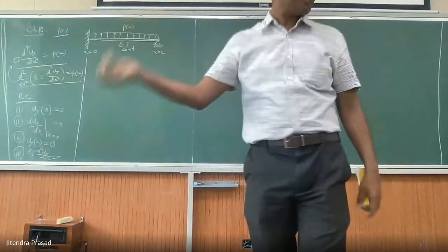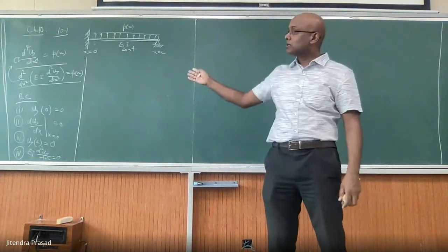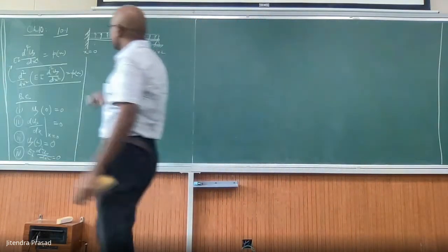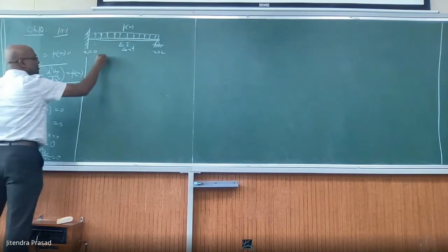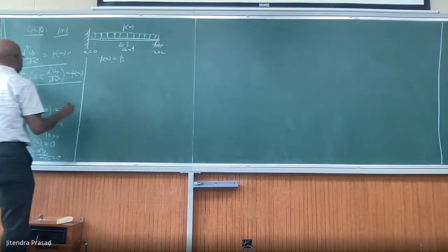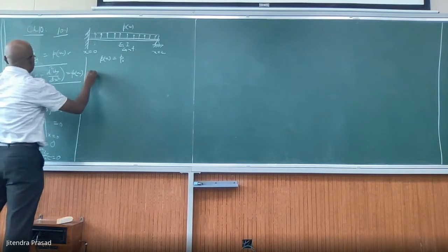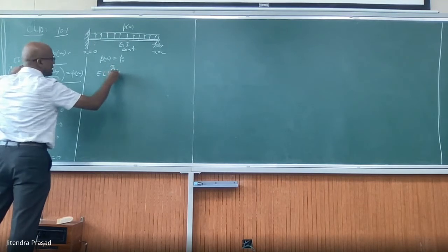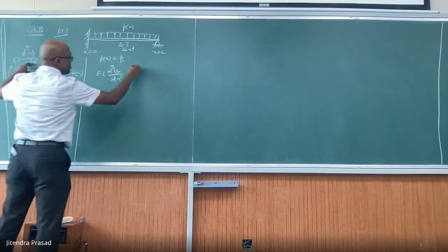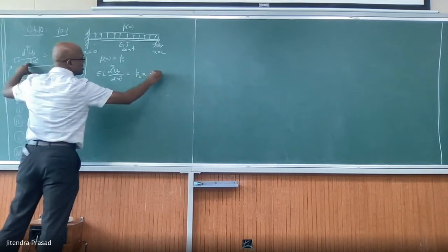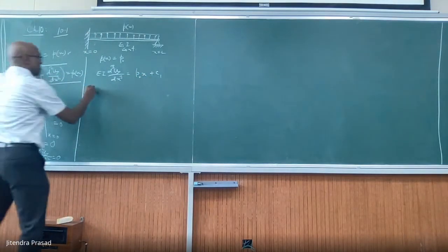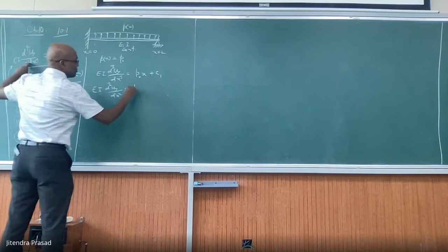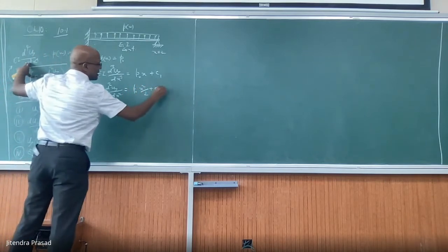That is the solid mechanics. I hope you will be able to do it, right? This is a differential equation. You have to solve it where p(x) equals p naught. Finally, EI d³uy/dx³ will be equal to p naught x plus c1, and so on, right? You have to keep on working, and EI d²uy/dx² is equal to p naught x² over 2 plus c1 x plus c2.